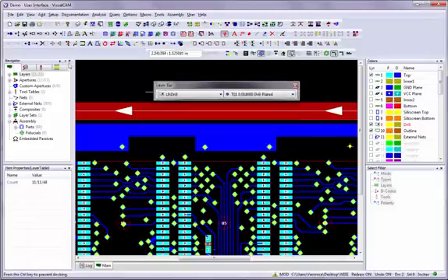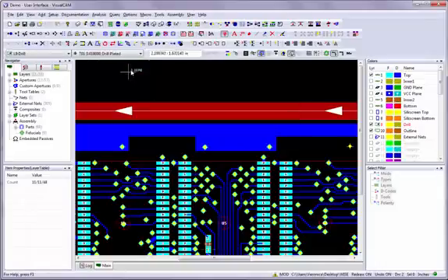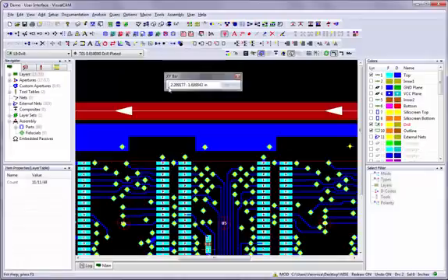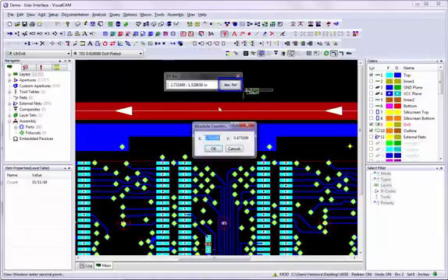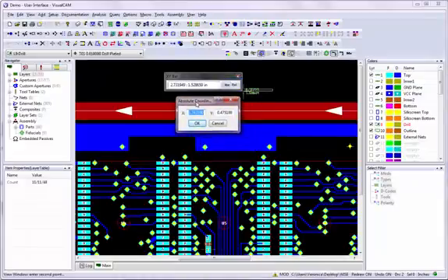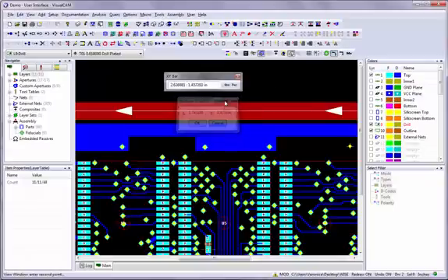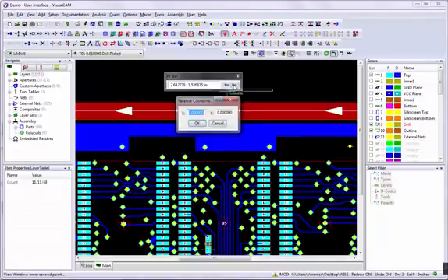Next, the XY bar shows the X and Y coordinates of your cursor in the workspace. The ABS and REL buttons allow you to change the coordinates to absolute or relative. These buttons are available when you are in one of the Edit or Add functions. For example, you would use the Absolute button when adding a flash at an absolute XY coordinate, and then use the Relative button to add another flash relative to the flash you just placed.